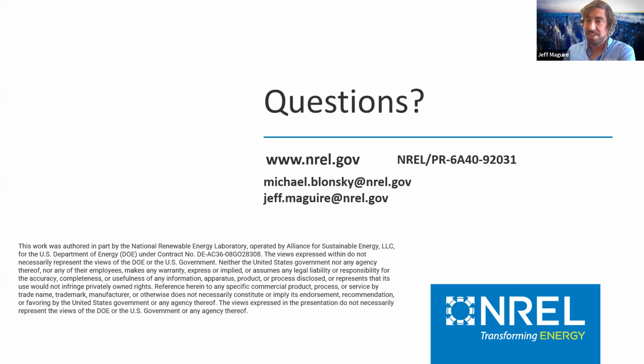I'll take this opportunity to mention one other thing that we are actively working on right now in terms of HVAC controls. We have been working with a student who's been helping us develop more advanced controls for when the electric resistance backup on a heat pump triggers, and to make sure that we are realistically modeling when backup triggers, compared to how real thermostats would control the electric resistance backup.